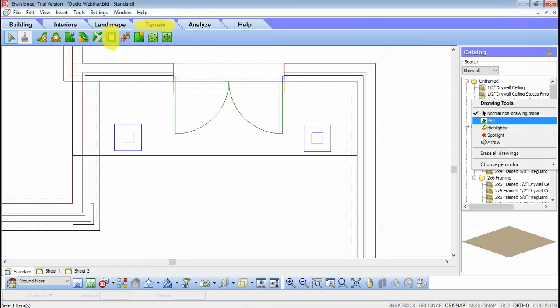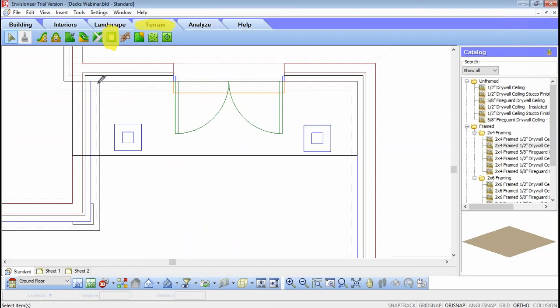So as we're looking at this in 2D, what we're going to do to insert our pad is we're going to use it and click different points to outline the shape of our pad. So I'm going to click 4 different points. We can see here that I've got snap points on 3 corners. This point right here is going to be a little bit tougher because we don't have an actual point to follow.